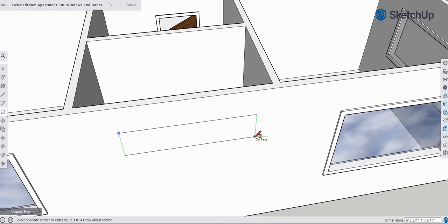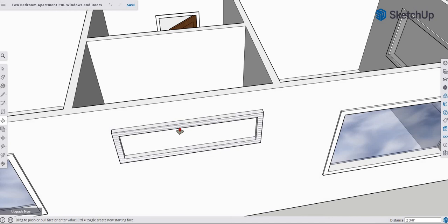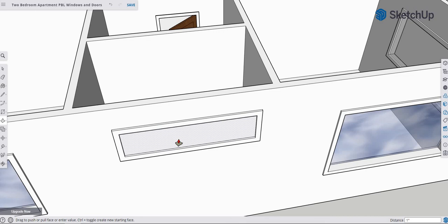If you do this, I will be happy. And tap F. I was trying to get fancy with stuff inside of it. We're just going to go right here. We're going to go on edge on the inside. We're going to go outside 3 inches, enter. And then take the push-pull tool, grab this, pull out 1 inch, hit enter. We're going to push the inside.